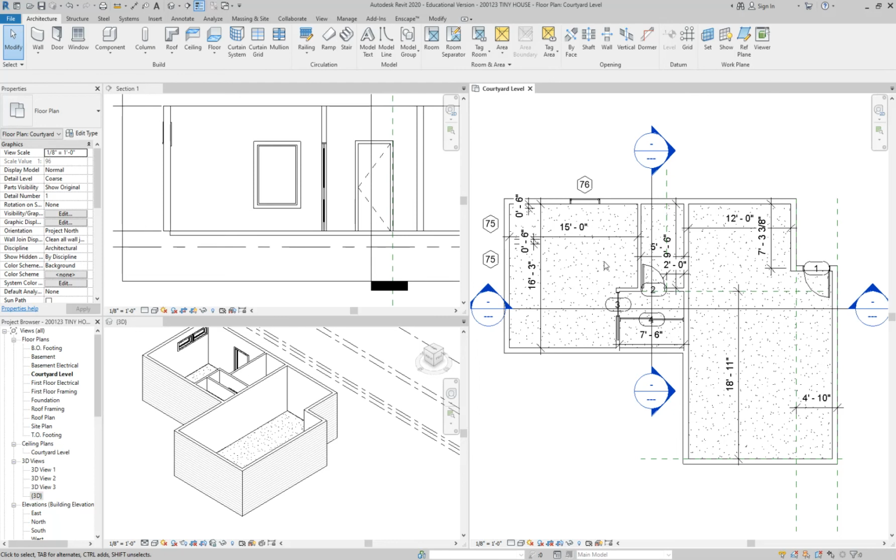I had to undo all my floors because when I went to save, it said they can't intersect. So now I'm trying to do the boundary line, or pick walls. How do you execute it? I click pick walls and then I click on the wall. As soon as it highlights blue, you should be good to go.